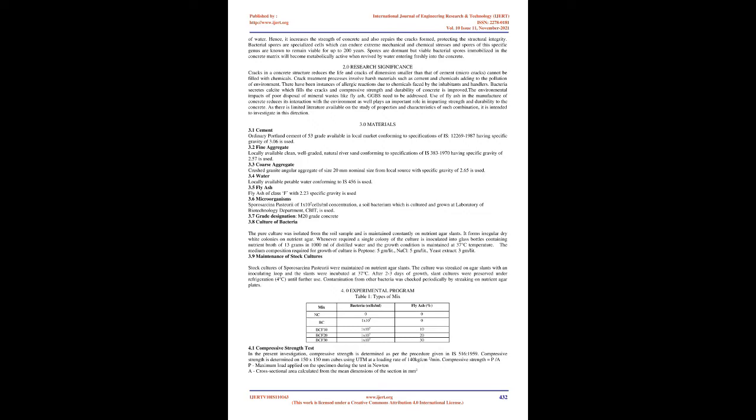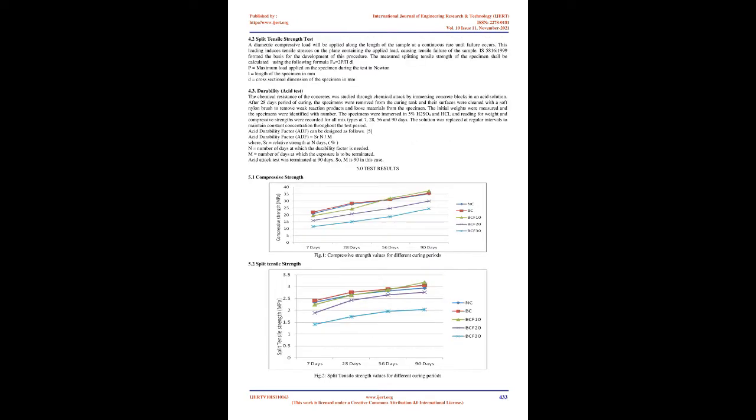For structures which are exposed to seawater or salts, the initiation period is a major concern. The initiation period is defined as the time taken from initial exposure until a concentration at the reinforcement able to initiate corrosion. The largest economic benefits are obtained by prolonging the initiation period through a proper durable concrete mix, smart structural design and proper on-site placement of the concrete, among others.